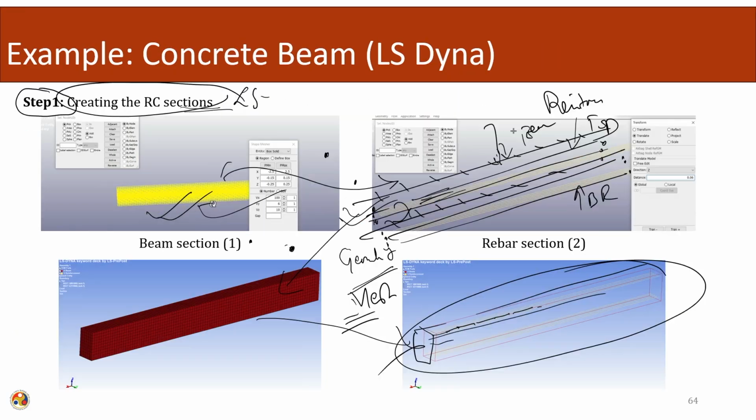Before we go into the post processing, one more good thing about LS-DYNA is that it is unit independent. Till now, from the starting, there are no units anywhere. You only see pure numbers. There is no unit in LS-DYNA. Whatever numbers we put, we have to choose a consistent unit ourselves. Let us say I choose kg for mass, meter for length and second for time. These are my chosen units.